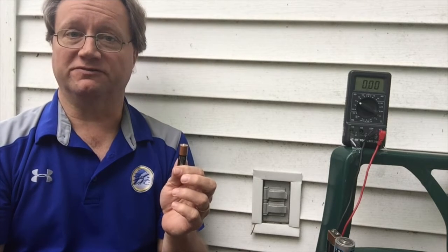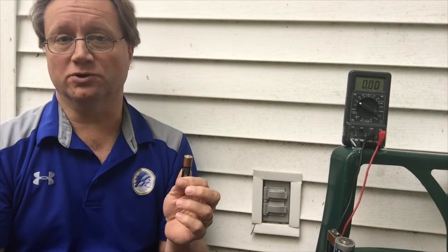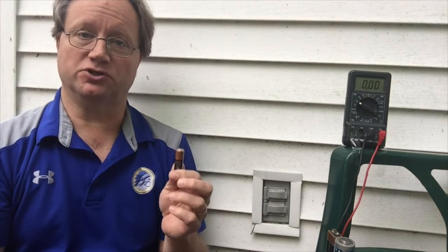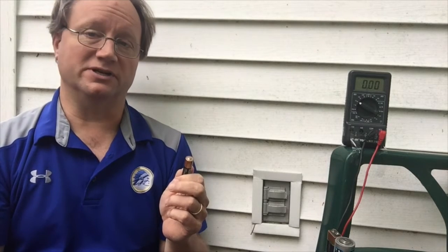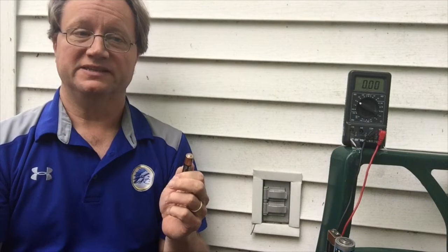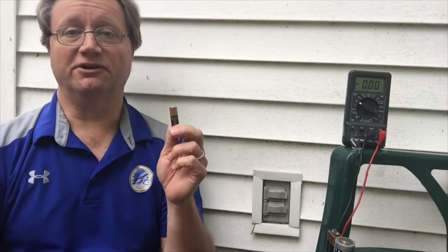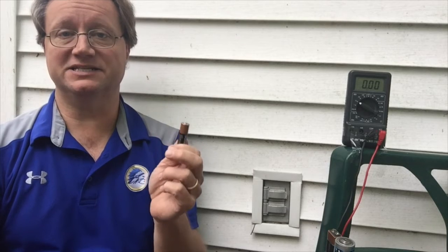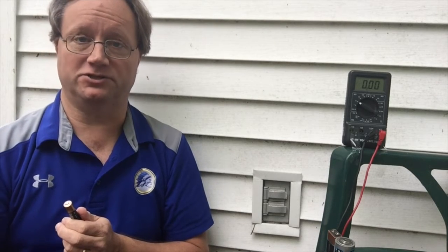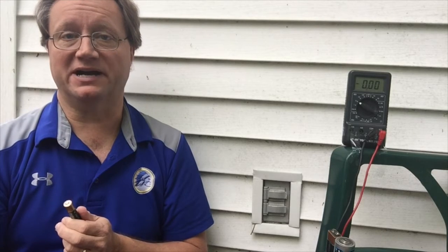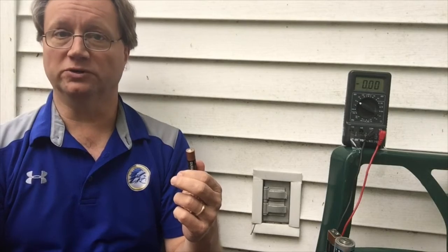Those charges that flow are able to do 1.6 joules of work for each coulomb of charge that is made to flow in the circuit. So if that's running, say, a light bulb, then you're able to get 1.6 joules of light energy for every coulomb of charge that this battery causes to flow. So when you're thinking about voltage and interpreting it, what you need to think about is whatever the number is in volts, joules per coulomb.